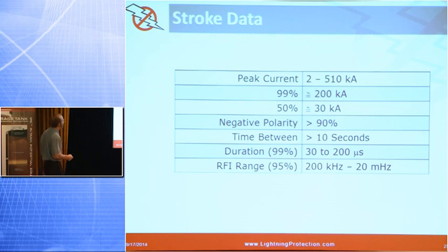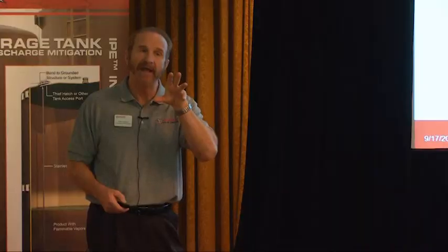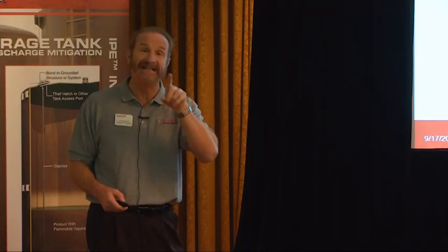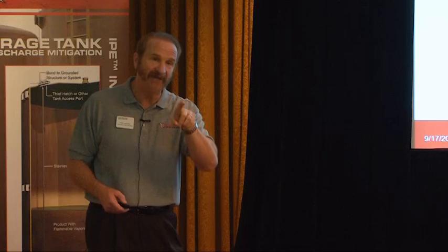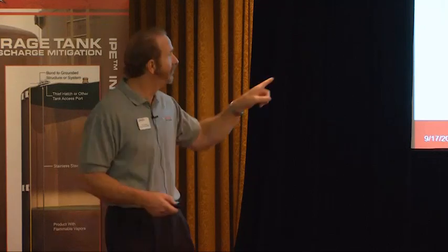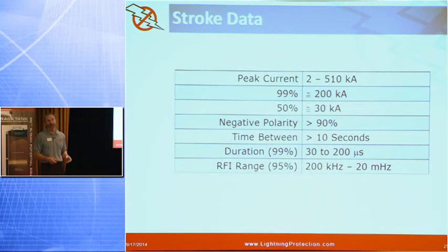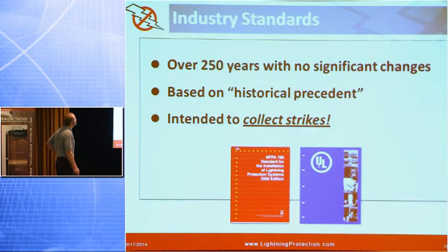And it's a high frequency. I always like to point out the fact that lightning is a high frequency. Even though we're talking about positive and negative, when it discharges, it oscillates. So if you have a high inductance path for that current flow of a lightning strike, even though it might look like it's very low resistance DC, if it has an inductive reactance to it, it's a high resistance to that frequency, and it won't be the preferred discharge path. So any kind of a discharge path you have, you want to make sure that it's a low inductance path.